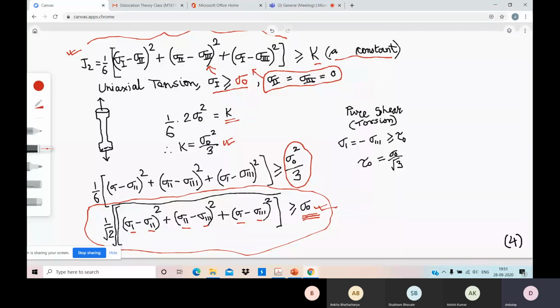So if you apply a certain kind of complex loading, 500, 300, 200, 200, minus 100, 0, if I give you three principal stress values, you can tell whether yielding will occur or whether yielding will not occur, provided you know the yield strength value for uniaxial tension.